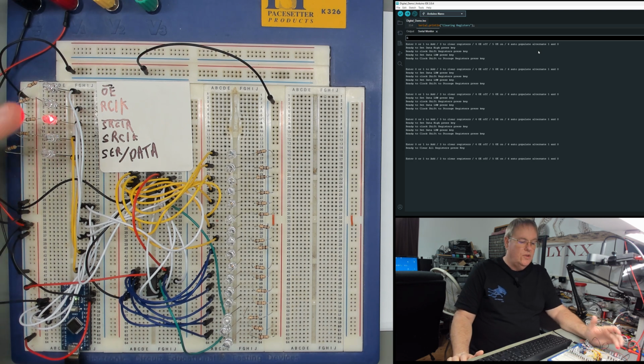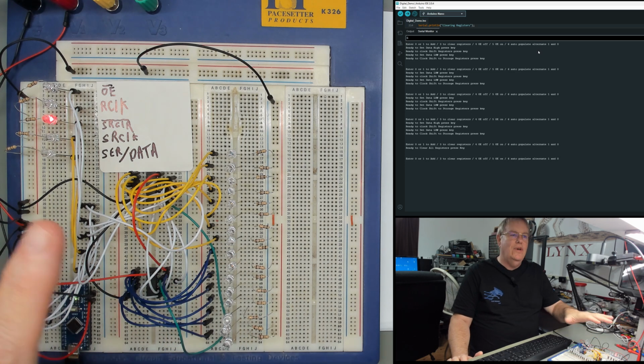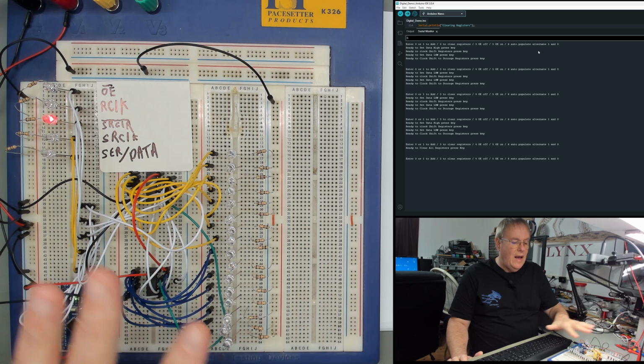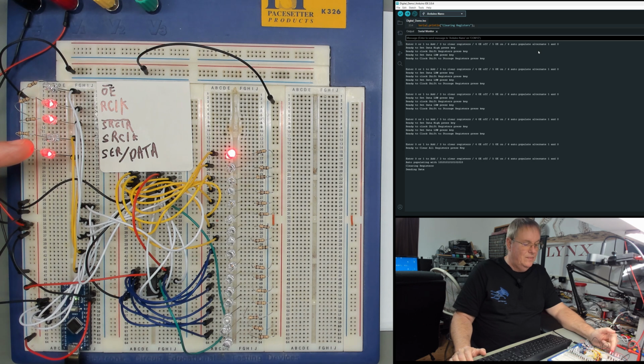You can actually watch the data and watch the pattern and how it's doing it, and it'll speed up as it goes. So by the time it gets to the last few, it's going to really move quickly. Here we go with 6. Clearing the register and starting to send the data now. There's a 1. Now it goes low here. It's clocking in a 0. Now a 0, it shifted it in. High, it shifted it in. Now it's going to shift it in.